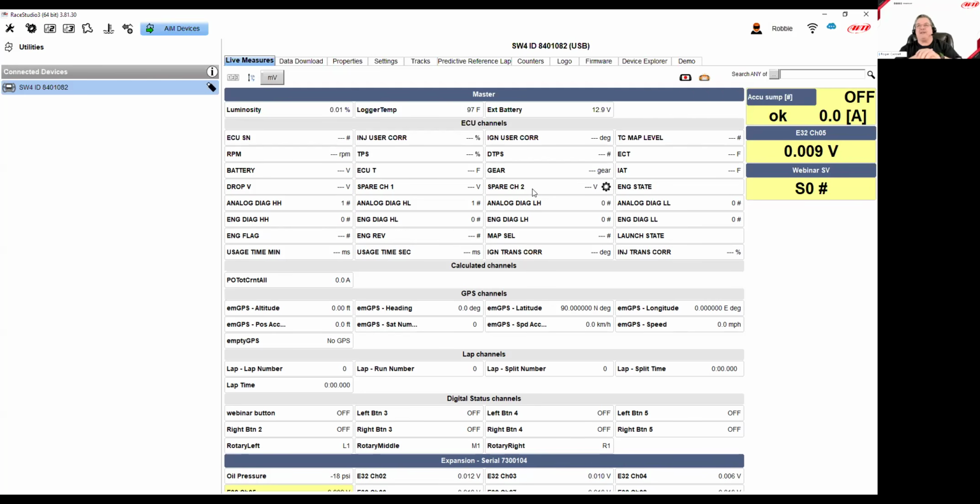Jeff asked a question, do the PDMs allow for user configurable analog channel filter options, setting the filter cutoff, for example? I believe that's a no as of right now, right? No, the only filtering mechanism that we have is like a desloshing mechanism for fuel floats. We have a few extra, pre ones like that, and of course we have all the ones in Race Studio 3 afterwards in post. But only a few. It is one of the things that I know I have been pushing for a little bit as well. So I think we're working on it.